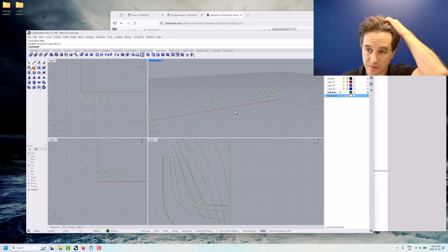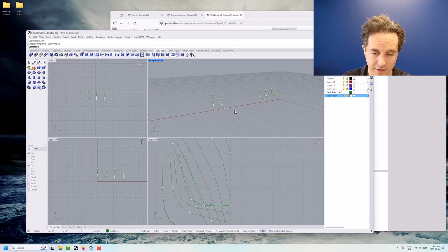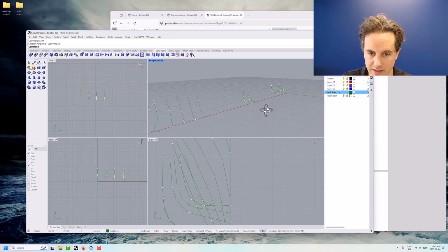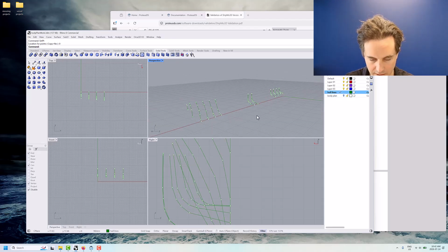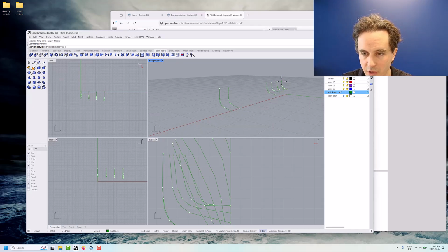Now there's a bunch of other functions in Rhino for making a surface. I found sweep2 works pretty well. To use the sweep function, we need to have 2 rails for the sweep to follow along. So we're going to make a new polyline. Oh yeah, and it's probably good to turn on OSnap here and make sure we have end and vertex selected.